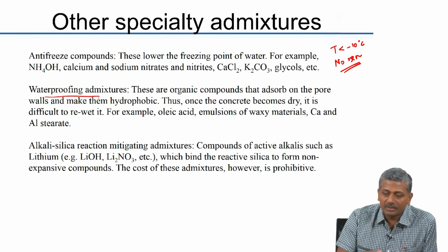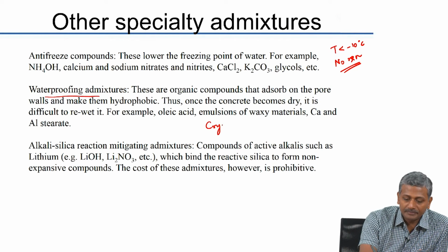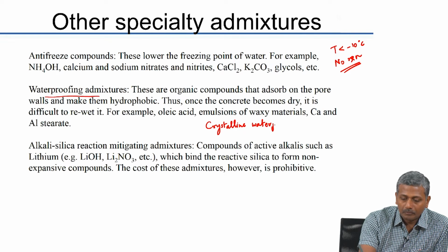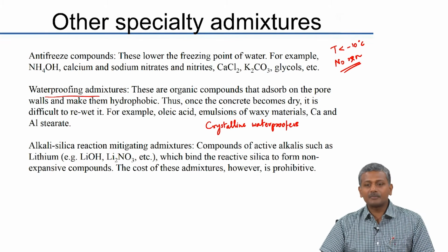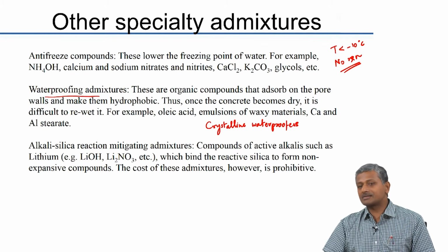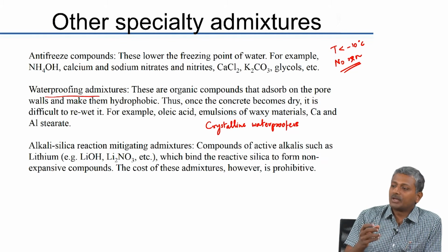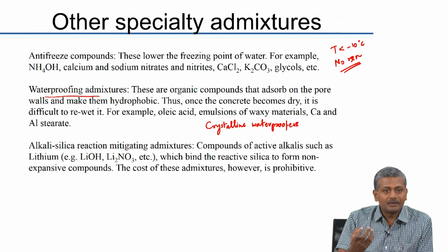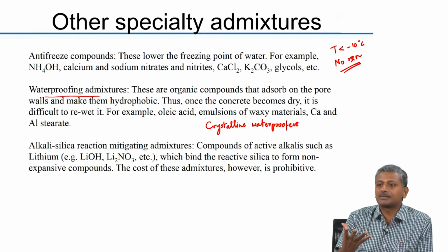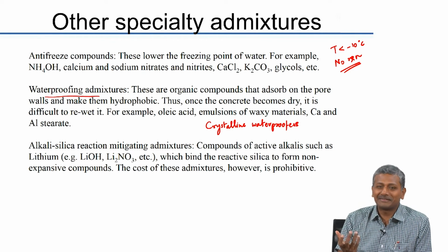One thing which I have not mentioned here, which may become quite popular when you guys practice, is the crystalline waterproofing admixtures. Now, again, as per the claims of the construction chemical manufacturers, these crystalline waterproofing admixtures are those which are added to the concrete, and whenever they come across a void or a pore or a space where growth can happen, they start growing into much larger crystals, and that sort of ends up blocking the pore. Sounds like science fiction again, right?